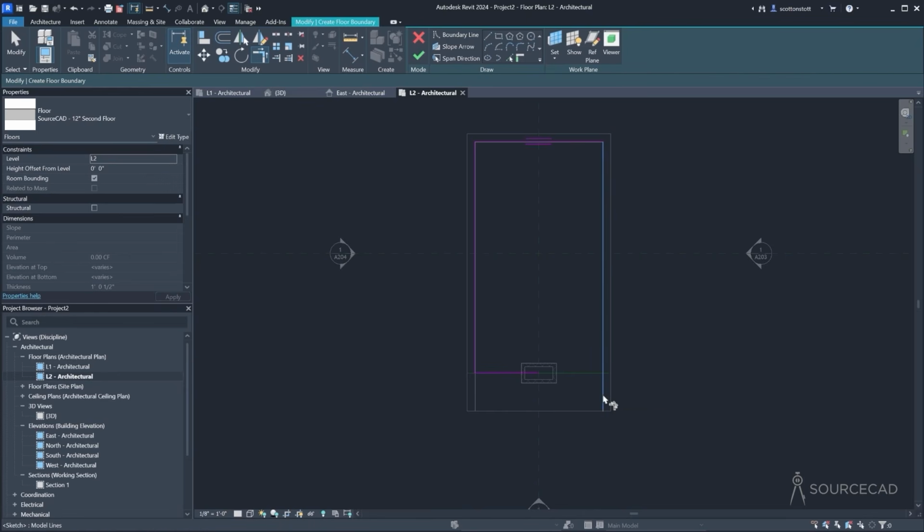So if I were to click this line here, and then this one here, it joins them in the corner. But because I click this line down here, it's going to leave that segment. That's not really what I wanted, though. If I click this one and this one up here, they get joined together. And if I click this line up here and this one down here, then the parts that I click are the parts that will remain in the end. That's how you use trim. Trim is used all the time when you're sketching. It's the primary way that you connect things together.